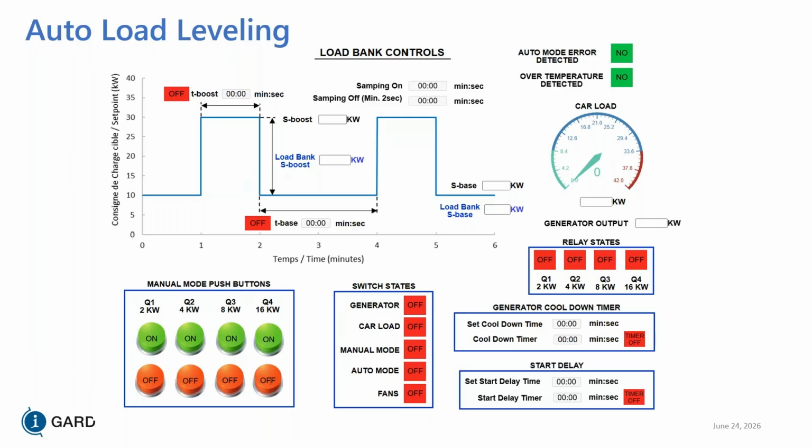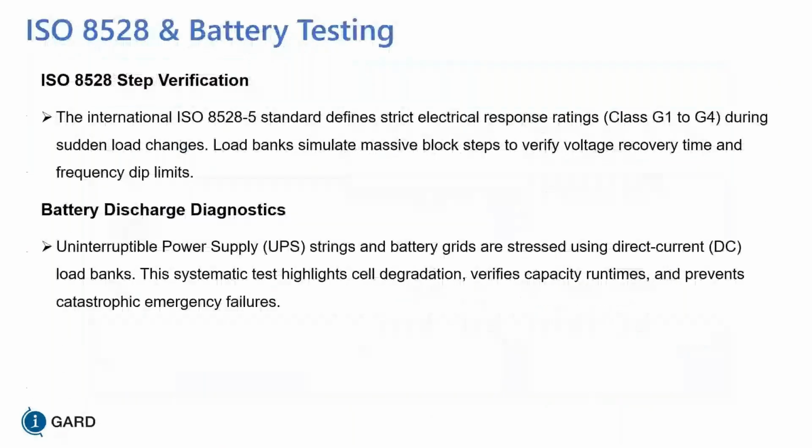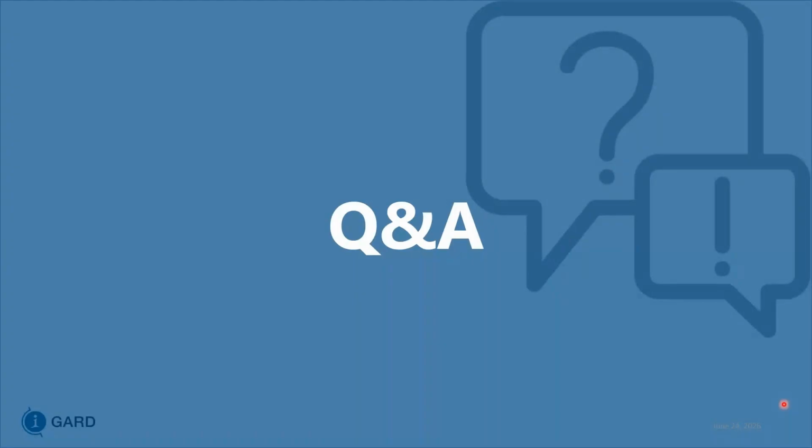Voltage is adjusted so we can use the same load bank. Can we use the same load bank for 480 and 600 volts? Yes, you can, and there are two ways of doing this. One is to adjust the load so you get the same wattage output for the 600 and 480 volts. The other method is to keep the load bank consistent, and the 480 volt will be 64% of the wattage of the 600 volt.